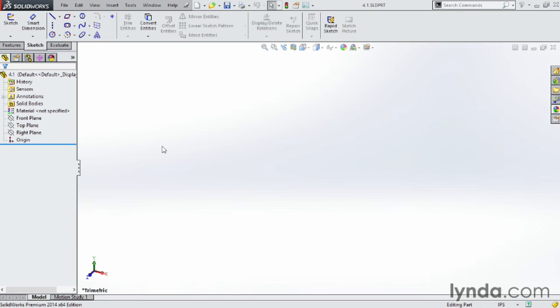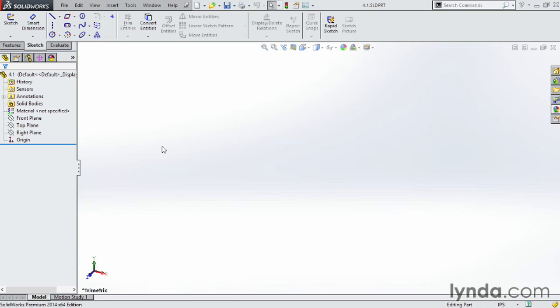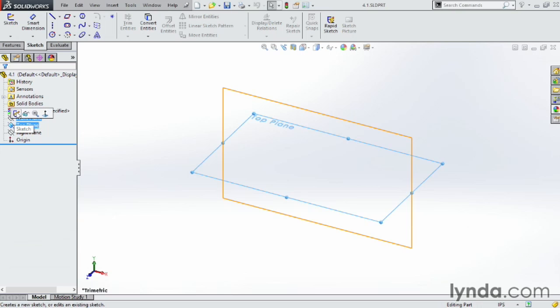The rectangle command is nothing more than 4 line segments and some relationships auto-created by SolidWorks. There are several types of rectangles preloaded into the SolidWorks tools, and we can use them, or we can create our own. Depending on the tool we use, the relationships are added differently.